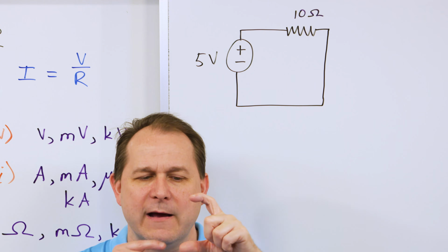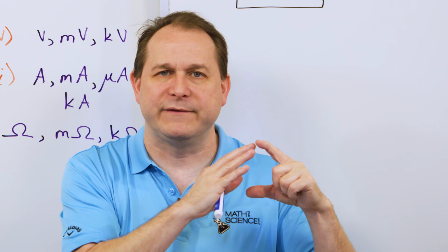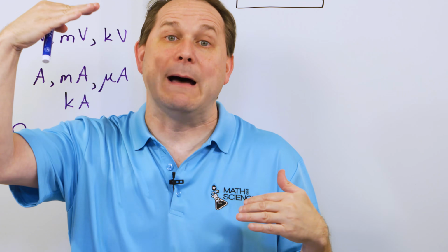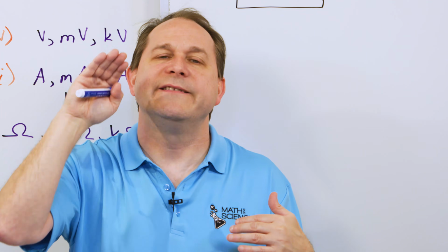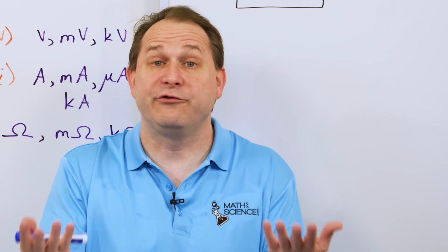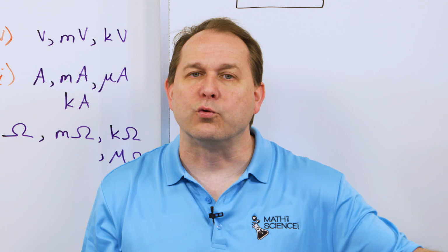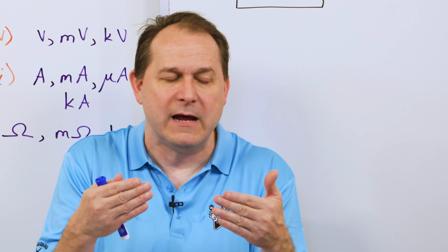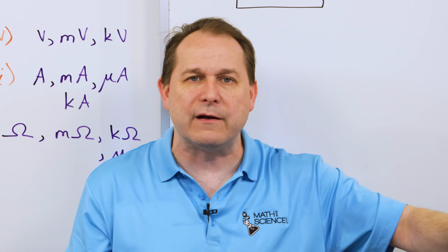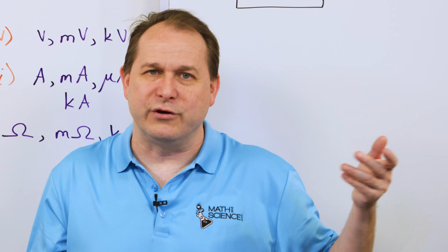If you think about a battery, you have the bottom and you have the top. And I told you in the last lesson, the battery was like a mountain. The top of the battery is like the top of the mountain with the potential to do work, sending the electrons out. When the electrons get back to the other side, they don't have any more potential energy left because they've gone down the mountain. Same thing here at the red terminal, you're at the top of the mountain. And as you go through the circuit and back around, you're falling down in potential. When you get down to this terminal, you have no more potential energy left. Then it goes back into the supply and the process starts over again.